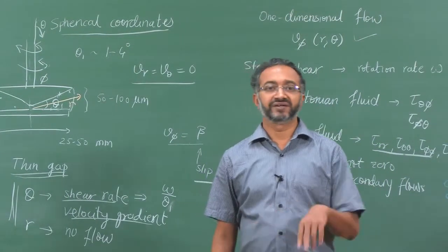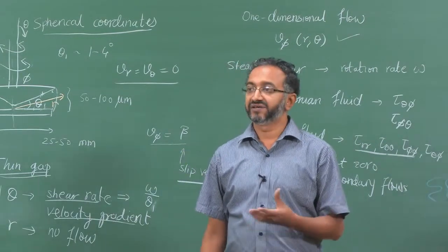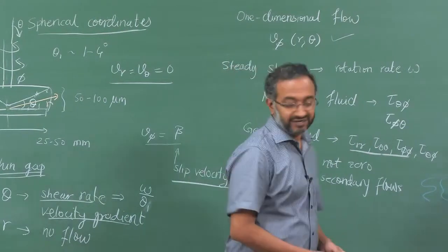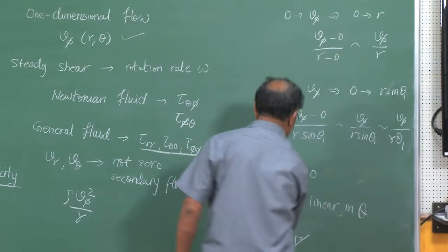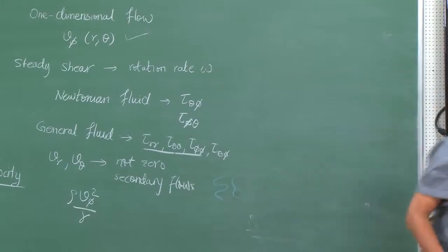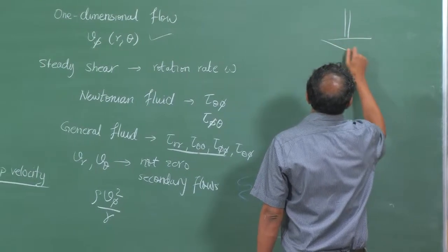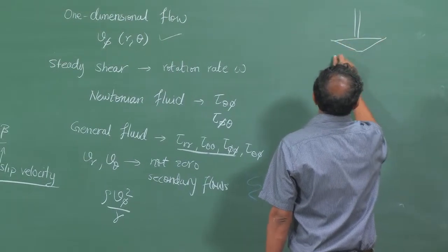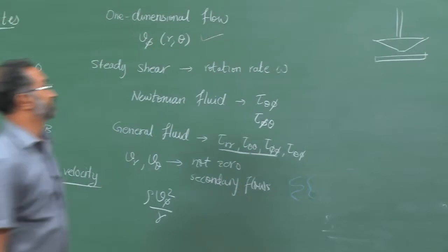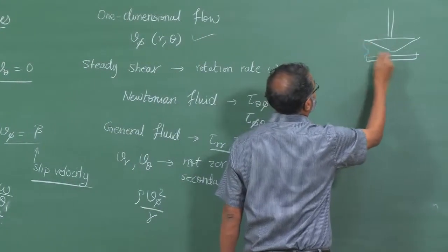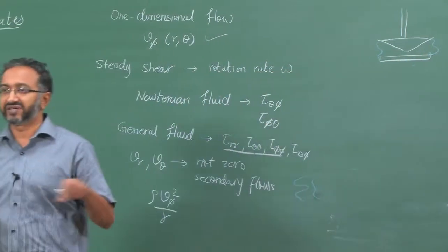One of the reasons why the uniform strain and strain rate may not be observed is the interface. As we saw earlier, if there is an interface and the interface starts fluctuating, then we may end up having non-uniform shear rates. If the interface itself develops instabilities and there is motion of it, if we have something like this, then we will have non-uniform shear near there, because there are secondary flows there.